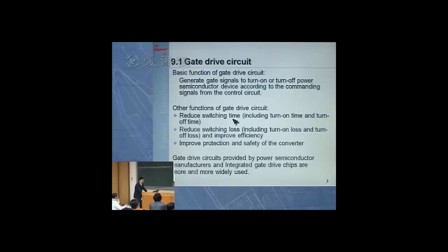Okay. If you have a better designed gate drive circuit, the switching time, especially the turning on process and turning off process, this changing process might be reduced. And also, if you have a very well designed gate drive circuit, you can also reduce the switching loss, the power loss during the turning on process and turning off process.